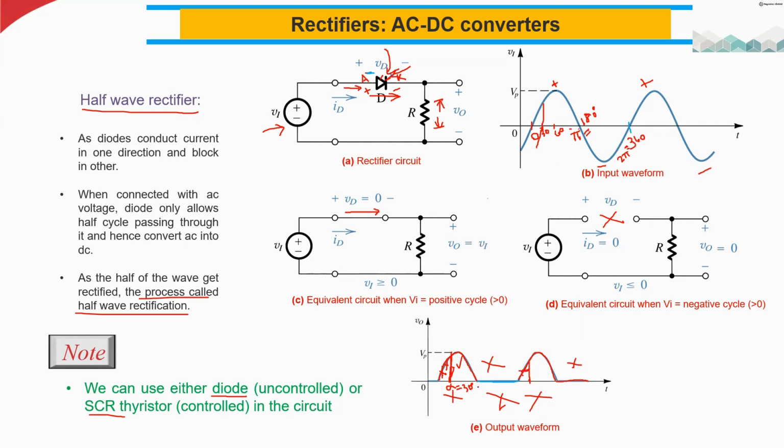And you can also increase or decrease this firing angle. By increasing and decreasing, you can change the output DC voltage. So what we are doing at the output is making an average value of all these pulsating DCs. So if you reduce the pulse width, for example, now I am putting 30 degree, right? So at the output, maybe as the average, I am getting plus 24 volt.